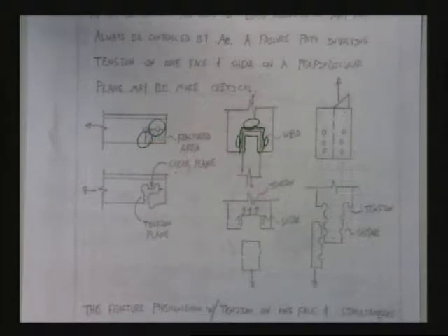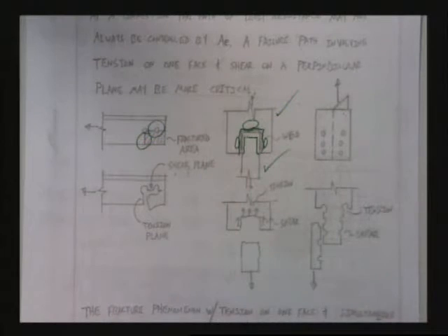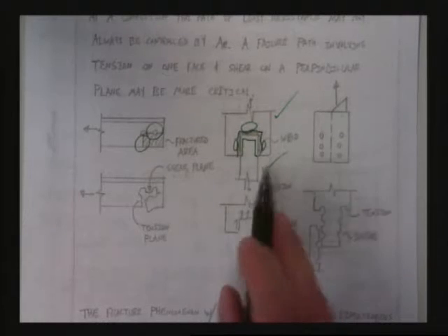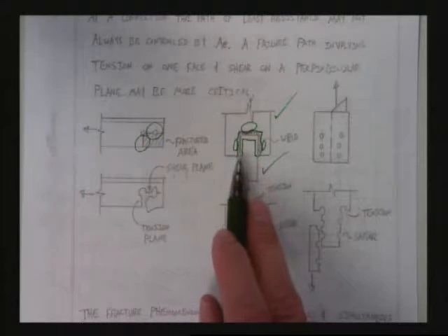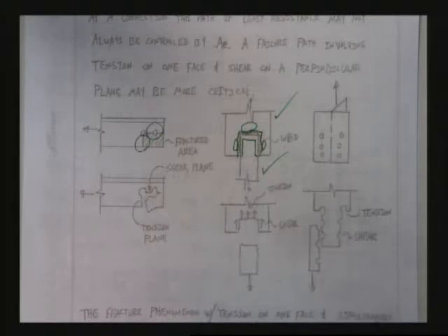One easy way to get around this is to make your gusset plate the same thickness as your member coming in, and you don't have to worry about it. In really, really big connections, or connections you're going to do over and over again, it is worth the time to do the math to see whether to not make them the same size, to maybe try to thin one up if you can. Depends. That's for you to decide.